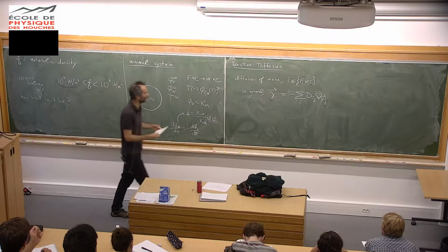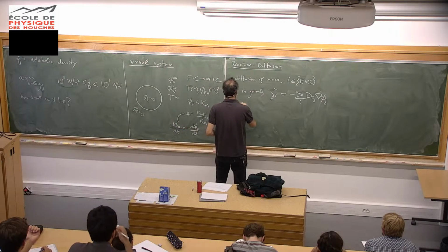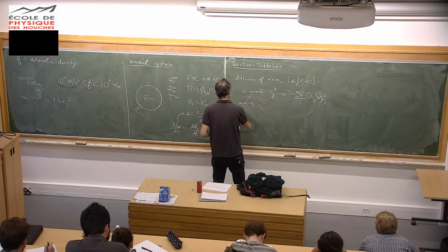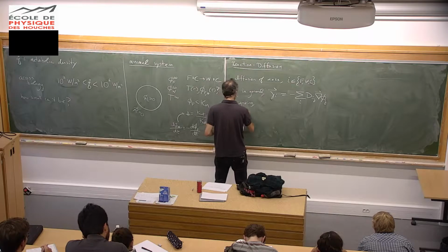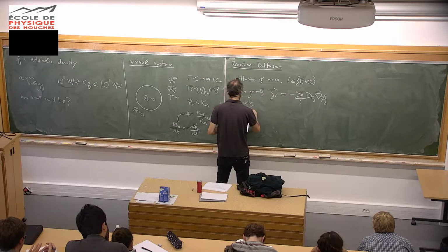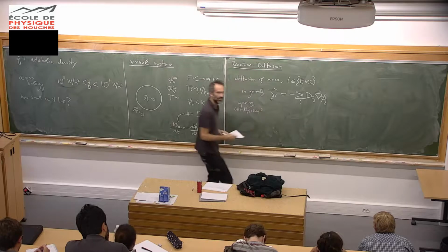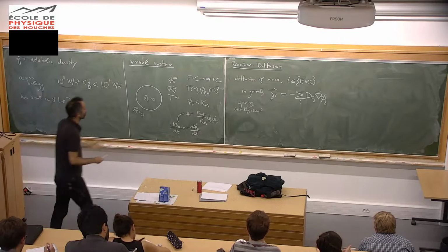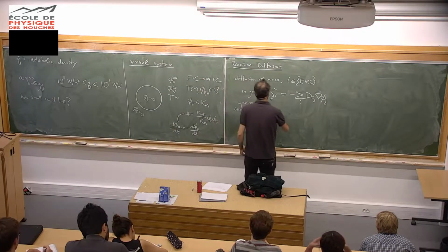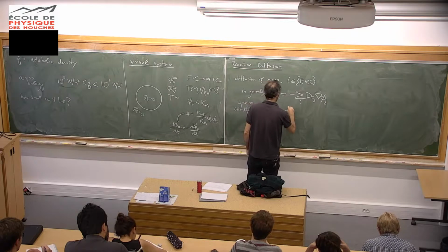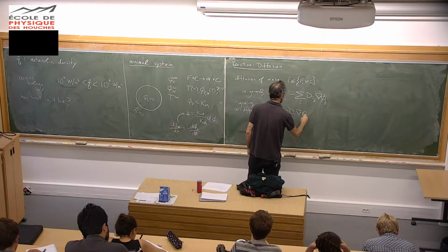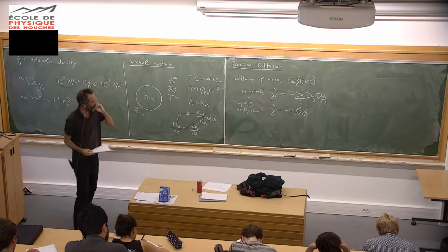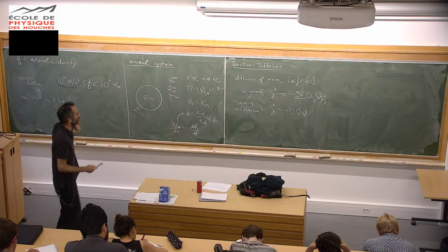But just to keep things simple for now, as an experimentalist, my general philosophy is you always use the simplest theory you can get away with for your data. And right now I have no data, so I just make it as simple as humanly possible, and I just ignore the cross-diffusion, okay? So if you ignore the cross-diffusion, of course, then we just have good old Fick's law for a single component. Okay, great. So that's the driving term here, gradients in the concentration.